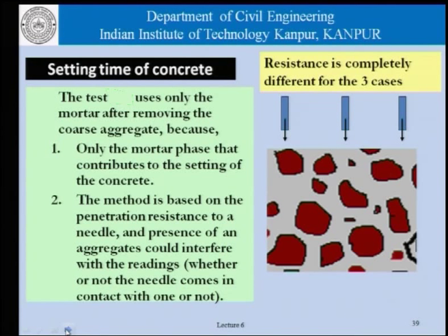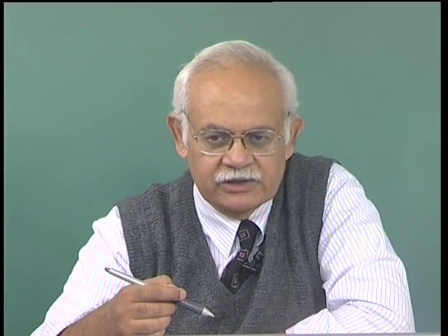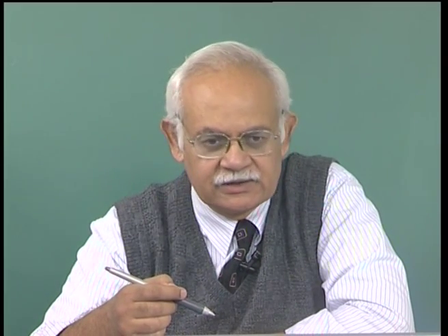When we are trying to measure the setting time of concrete, we said that the concrete is wet sieved to remove the coarse aggregate. Now, the logic for that is given here. It is only the mortar phase that contributes to the setting of concrete. The presence of coarse aggregate does not really affect the hydration process, and therefore we can neglect them or ignore their presence and just work with the mortar as far as the setting time is concerned.